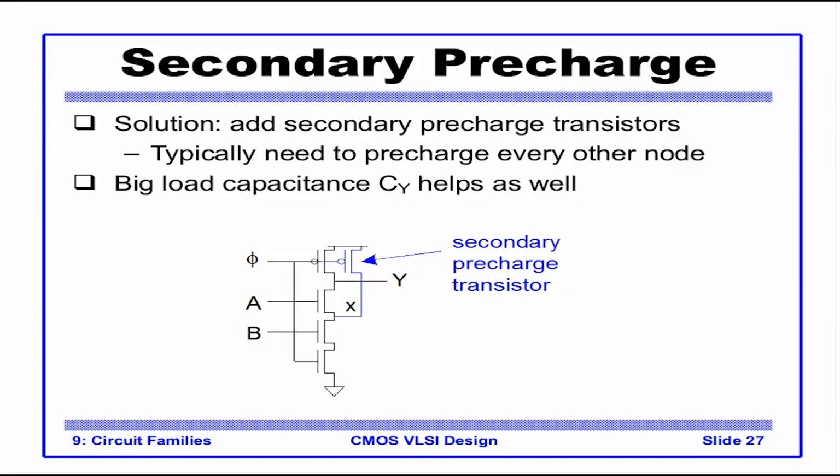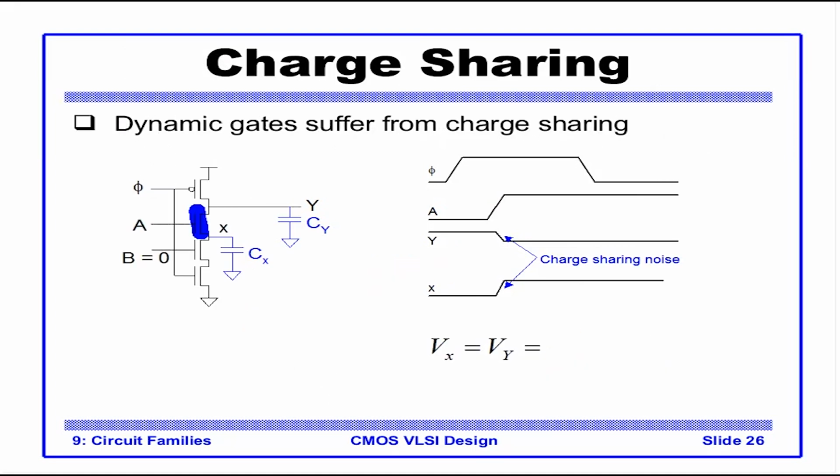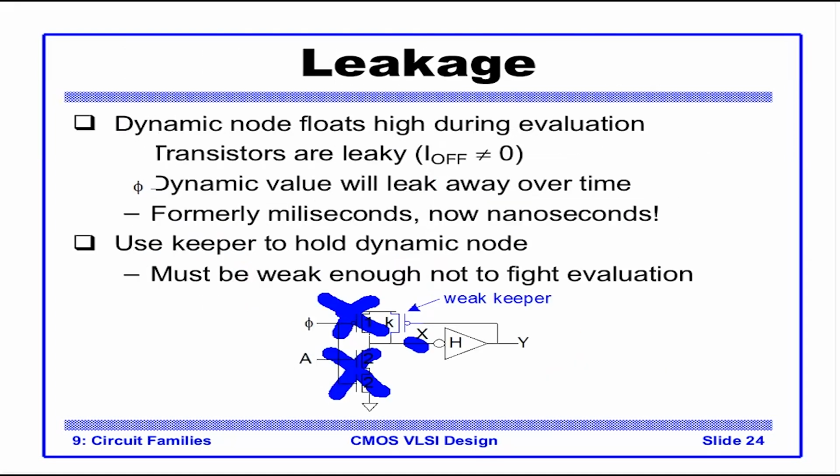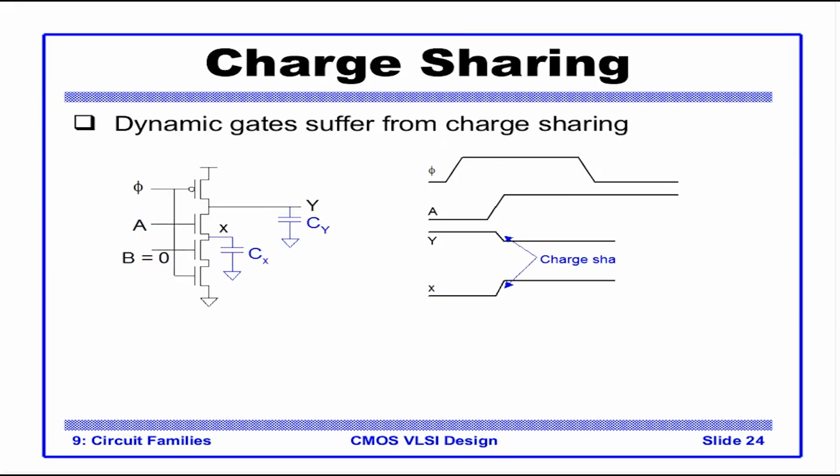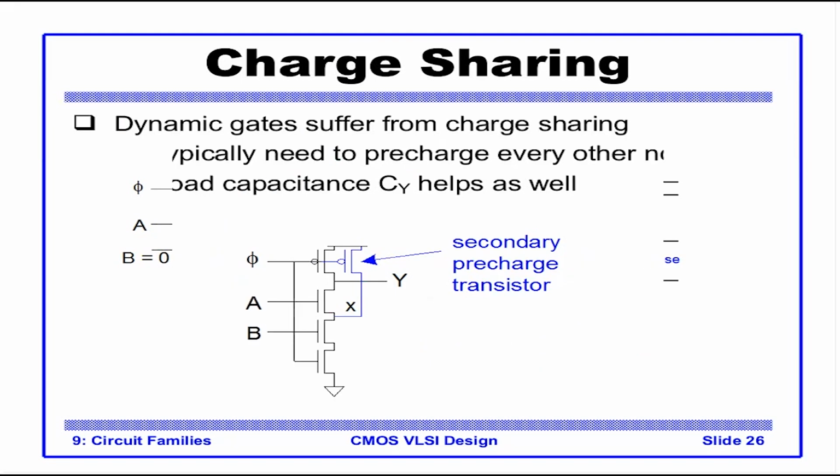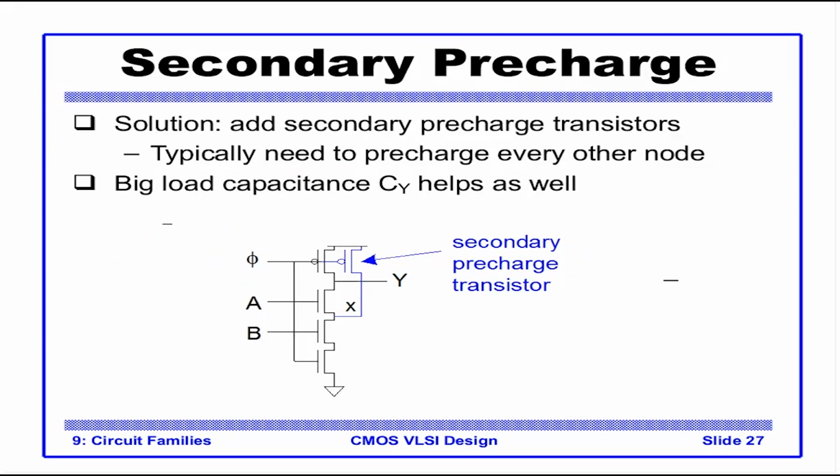So we saw one problem of leakage. How to solve it? We saw that we need to add a keeper. So see, now we are modifying a dynamic circuit to remove the incompetency it has when compared to regular static CMOS, and in turn we are actually adding logic. So here we added a PMOS to kind of recharge it. So the area advantage it has over regular CMOS is kind of decreasing now.